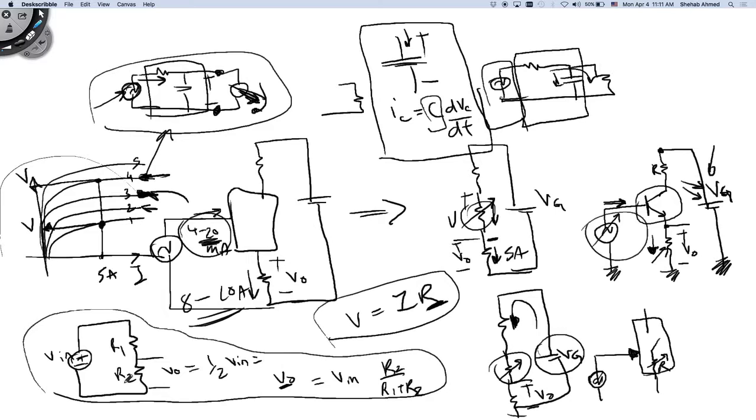I can make one smaller than the other or bigger than the other, and I can make one frequency dependent. Right? With low pass and high pass filters, we attenuated high frequency and let low frequency pass through, or we attenuated low frequency and we let high frequency pass through. So we did both gain manipulations as well as frequency dependent manipulations using simple passive circuits.